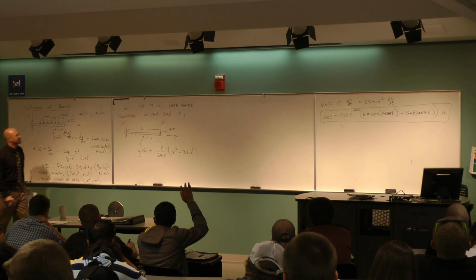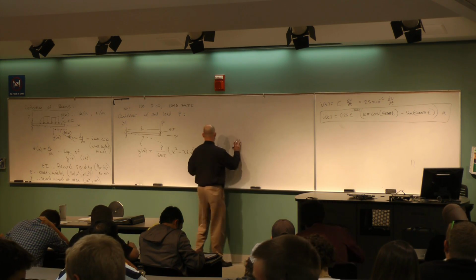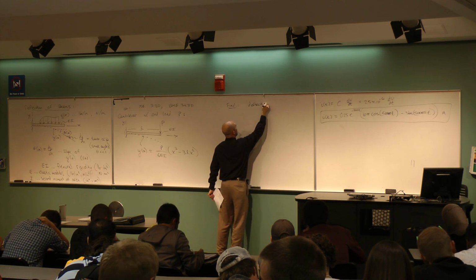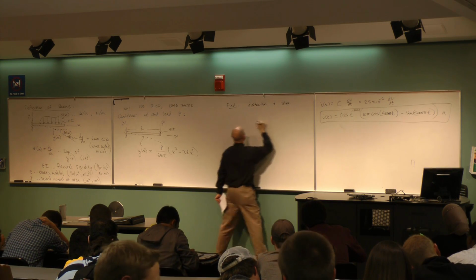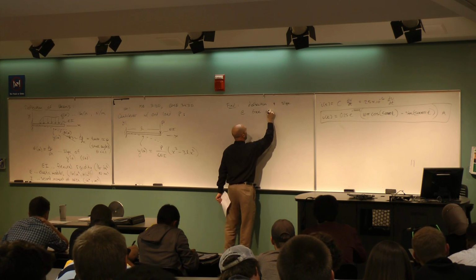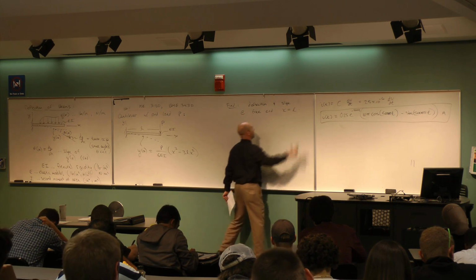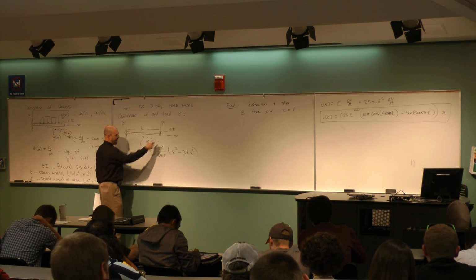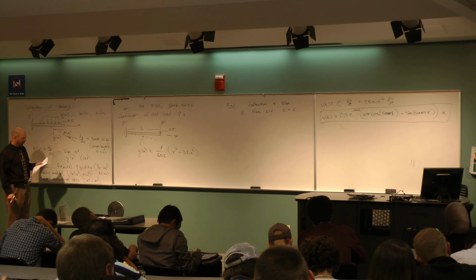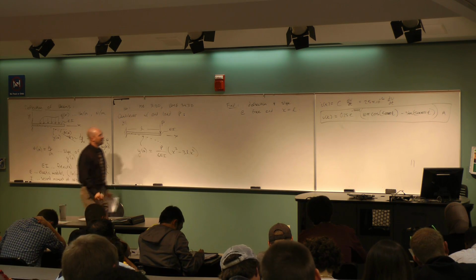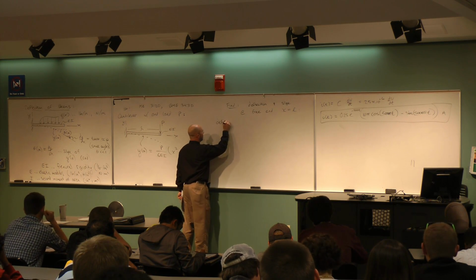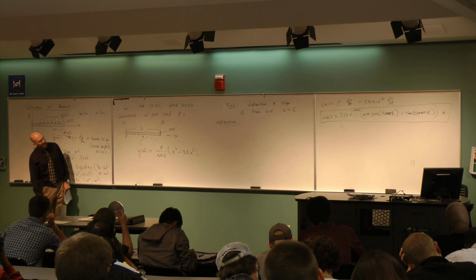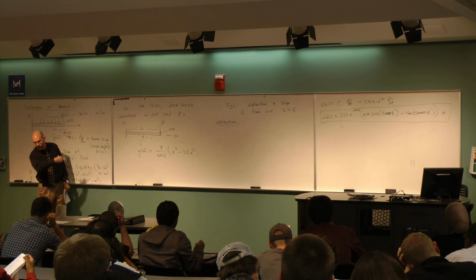All right, so what would I like to find? I want to find the deflection and the slope at the free end. So deflection and slope at the free end, which is x equals L. If I have y as a function of x, then x equals L is the value of the deflection all the way at the end there. What is y evaluated at L? So first part, deflection. If I'm given the deflection curve y of x, and I want to find the deflection at x equals L, do I need derivatives for that?